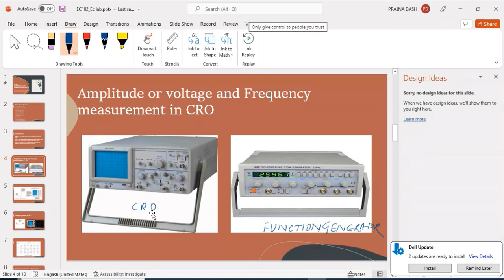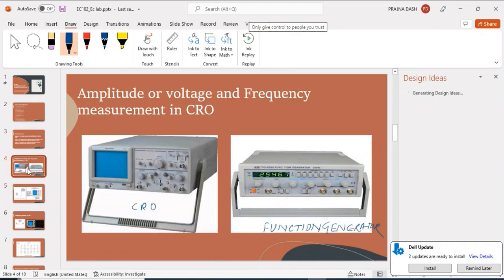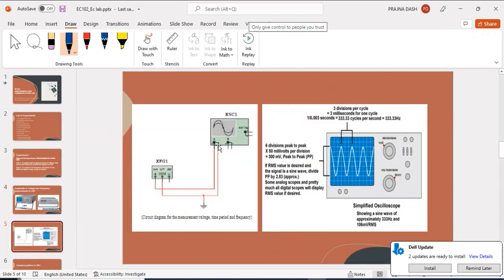When we connect that, this is the symbolical representation in the Multisim. This sinusoidal waveform display screen is already there, which means it is the CRO. Here this is channel A and channel B, the two channels I have shown you as channel 1 and channel 2. So in Multisim we will have this A and B channel, and in one channel you can give one signal. If you want to simultaneously visualize two signals, then you can use the other port also.